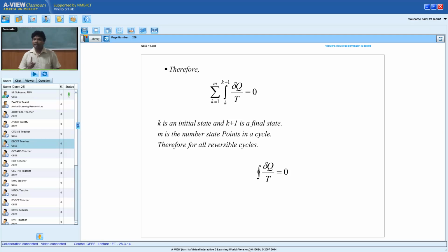The beauty is, see, Carnot says that achieving the goal need not be one way. So it looks like if you increase the compression ratio in an Otto cycle or a diesel cycle, or you increase the pressure ratio in a Brayton cycle, you can achieve the highest temperature of heat addition very easily. And hence that will fetch you good efficiency. But you should teach the student that because I am not able to practically achieve a Carnot cycle, what I could practically achieve is an Otto cycle, diesel cycle or a Brayton cycle, but Carnot's idea I am following. I'm not violating the Carnot idea. How to follow the Carnot's idea? Only by increasing the compression ratio.